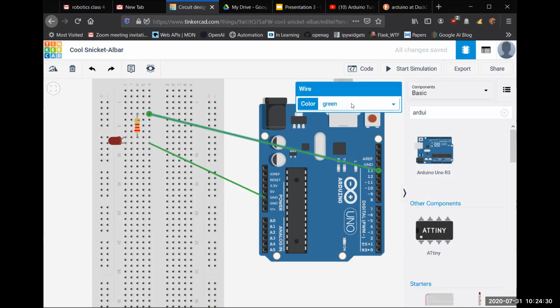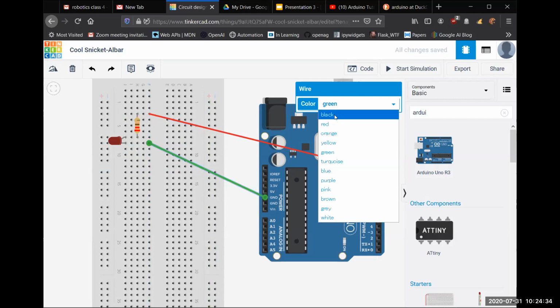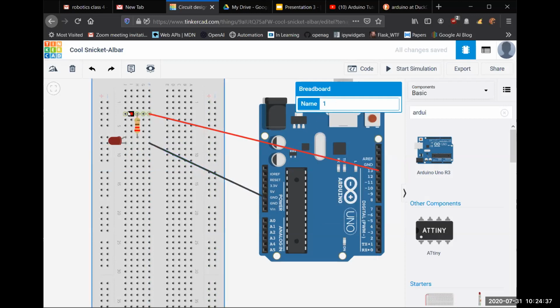The instances where you'll actually have a problem is when you're doing these connections. Always remember the direction of the connections on the breadboard. This is how they move. The lines here are parallel, number 1 all the way to number 60. So if you connect the resistor to this pin, then you'll also connect the other pin to this point here, and then also for this as well.